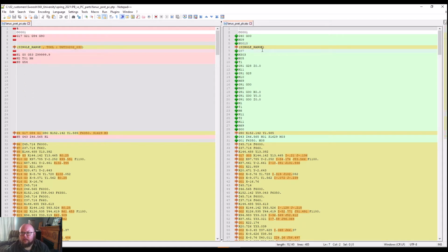And in this case, we'll see on Post Configurator we have an out-of-the-box note here, single range. That's our operation name. We're also getting a tool name in this little header. In Post Builder, we're only getting the operation name. So let's just go in and look at what it takes to do a little bit of modifications to our output.